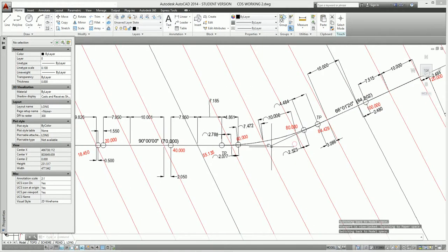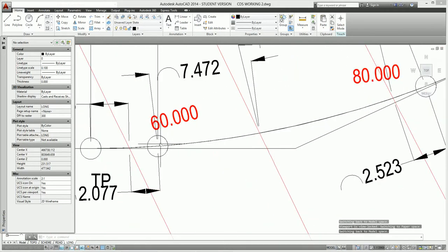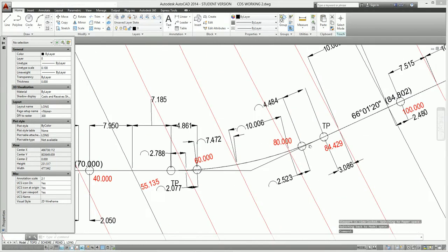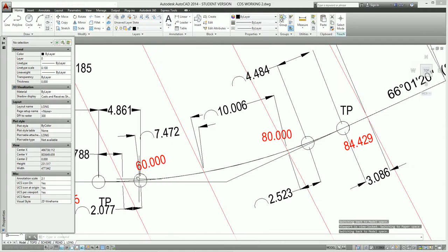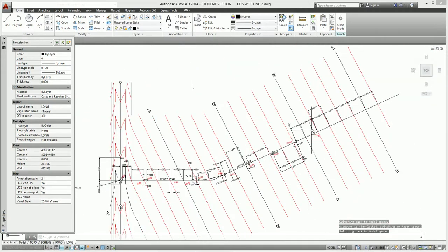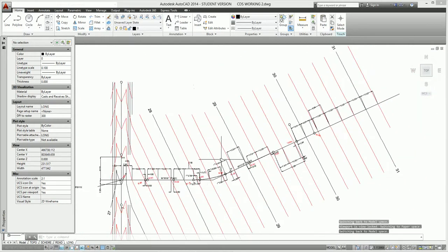And one of the other things that I also have done is, although we don't have heights at the actual points on the horizontal alignment, the horizontal points, I have keyed into those to make sure that our measurements are reasonably correct within a few millimeters. So that's how we're collecting the surface information. Now, how I've collected that is I have gone and used an Excel spreadsheet, and I'll just pause for a moment and then I'll come back.